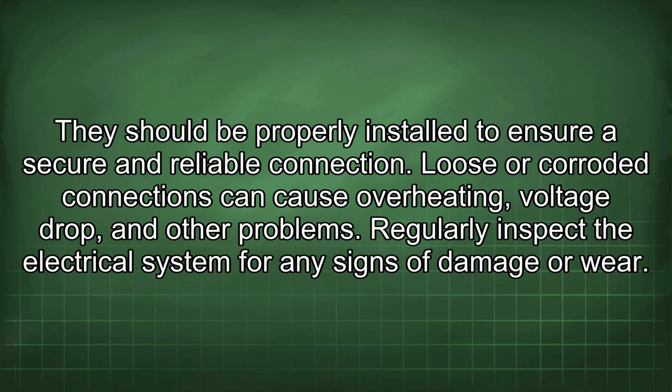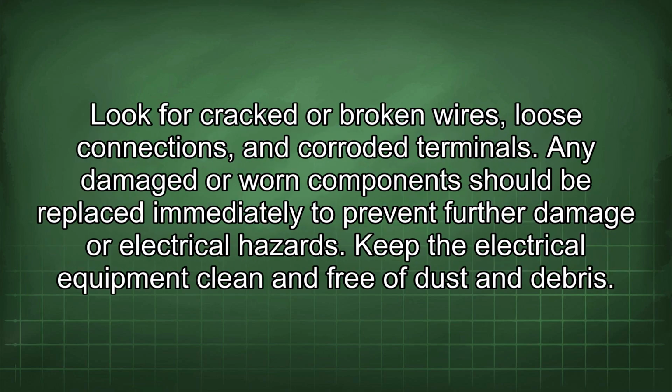Regularly inspect the electrical system for any signs of damage or wear. Look for cracked or broken wires, loose connections, and corroded terminals. Any damaged or worn components should be replaced immediately to prevent further damage or electrical hazards.